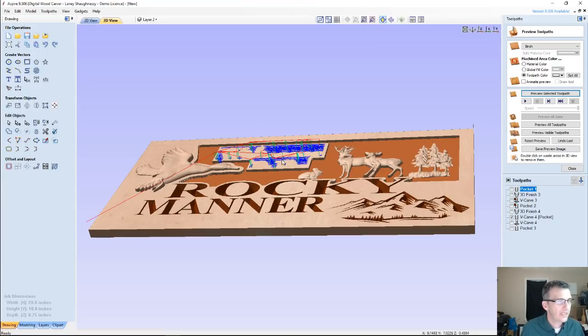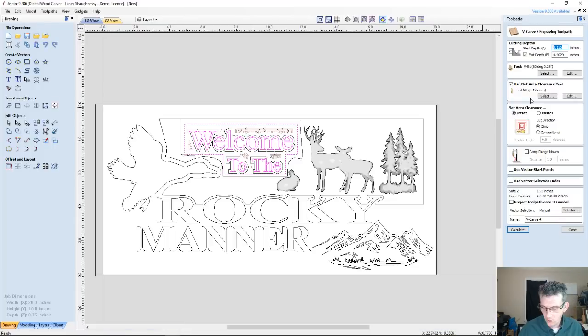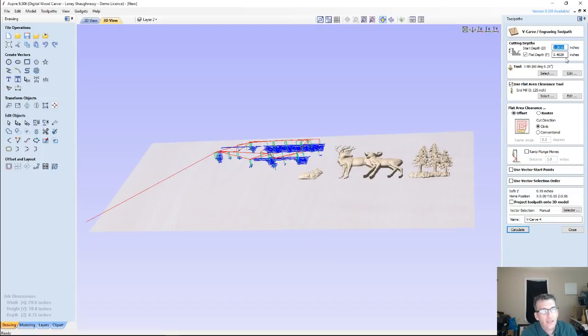Now, on that cut, I'm cutting down to essentially this is my 0, but the software doesn't look at it as 0. It looks at this depth here as 0.4884. I've got to start the toolpath down here and then end up 0.784 equals 0.2616. From there I need a flat depth down to where the rest of the models are.